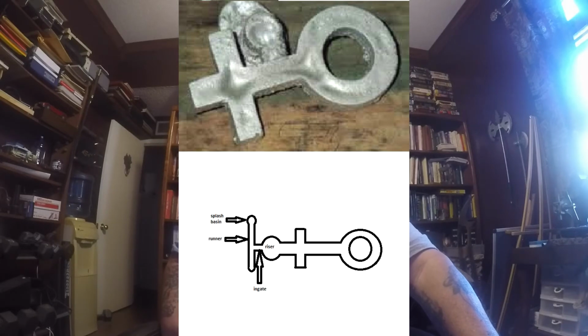Here we have a very good example of what might happen if you overheat your metal way too much. Now look how thick that casting is. That casting, the molten metal did not need to be any hotter than 1250 degrees. But I'd venture to say that whoever poured that, that thing must have been 1400, 1500 degrees for that shrinkage to take place like that. Especially it took place in the bottom of the mold, on the bottom facing of the mold cavity. I've never seen anything that bad like that.